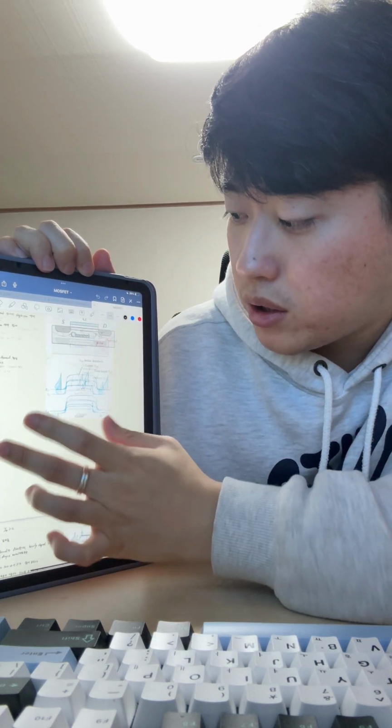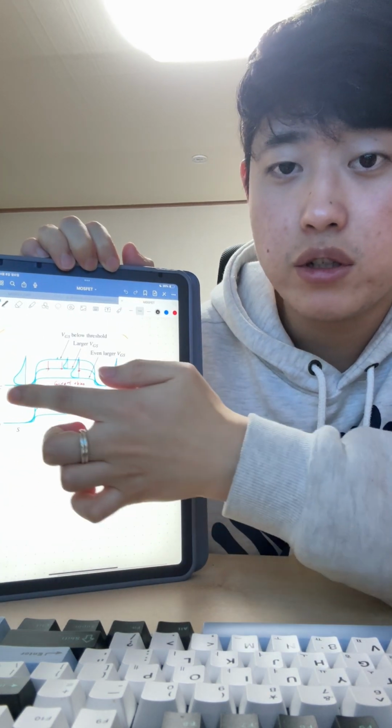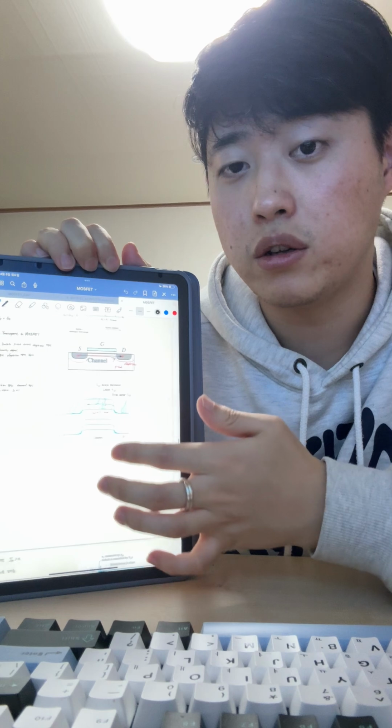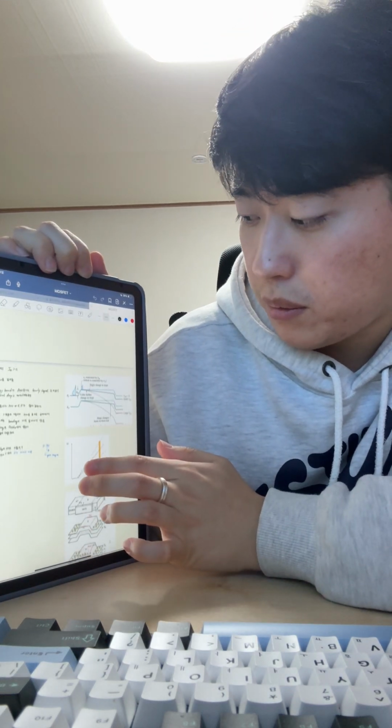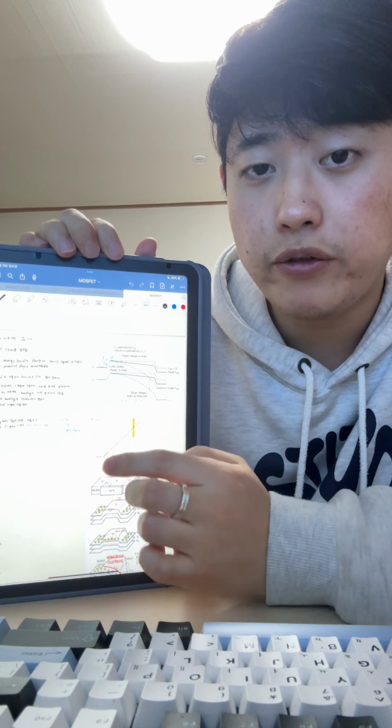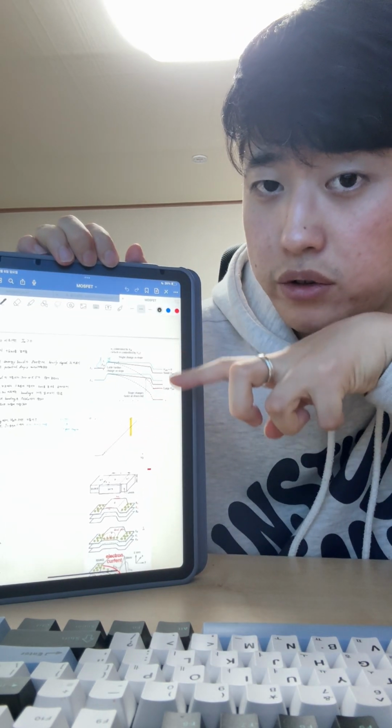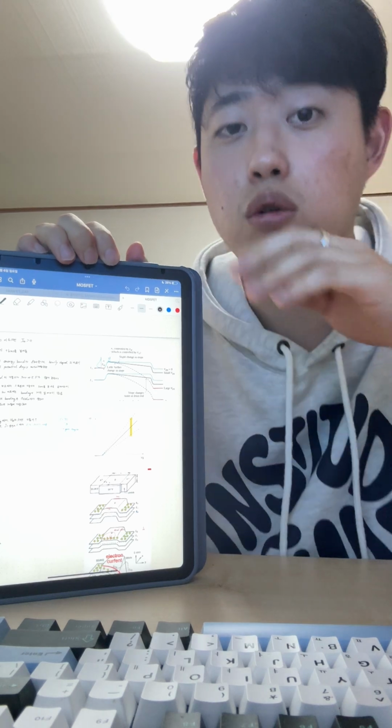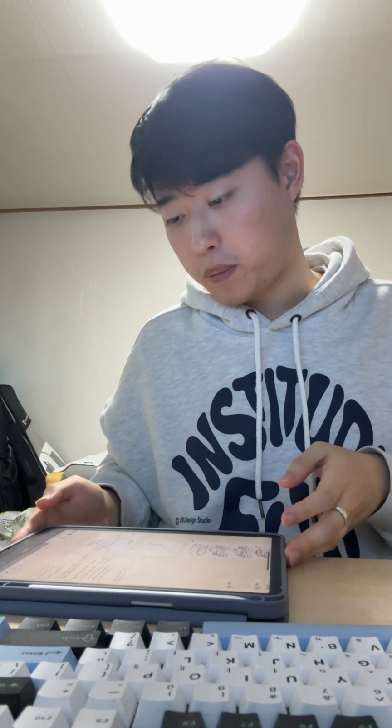But drain and source are equal, so there is no current in the channel. If there is plus bias on the drain, the energy level is lower, so there is an energy potential difference between source and drain. Electrons in the source go to the drain because of the potential difference. So more bias on the drain gives more current.